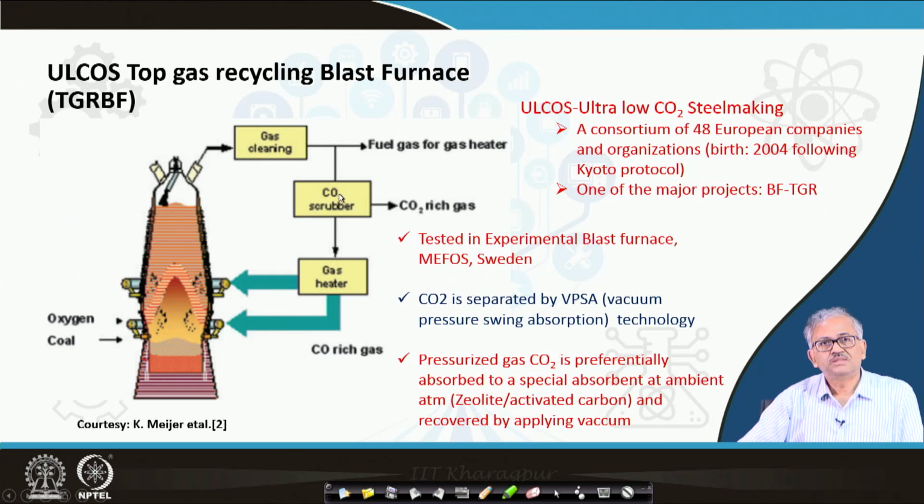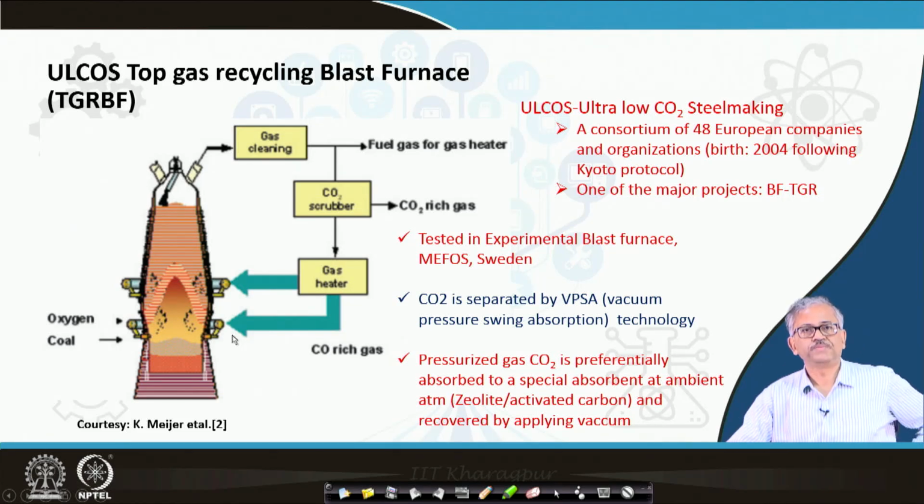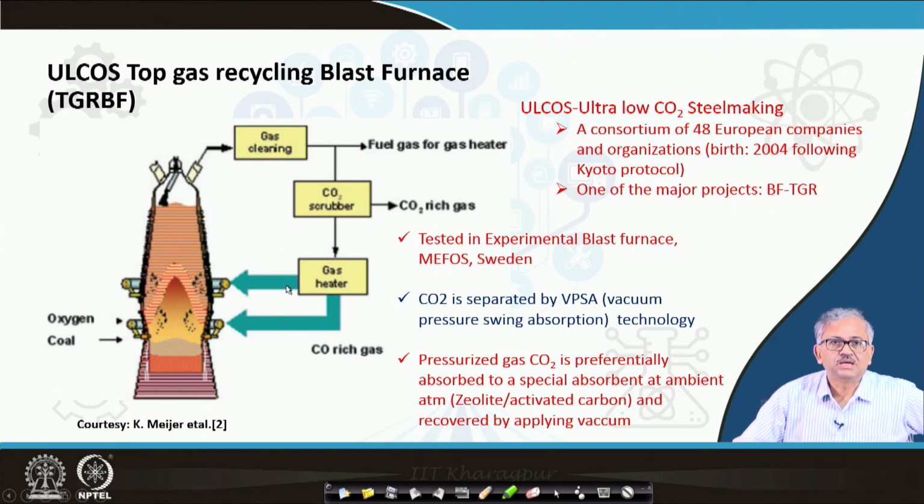But there is the CO gas, which you can push through the tuyere as well as in the shaft location. Also the heat capacity of the gas will decrease if you use pure oxygen, and then to meet the heat balance in the top part of the furnace, you can have some difficulties. But since we are recycling the gas, this gas is there, so heat capacity is maintained again. Okay, so that way it is there.